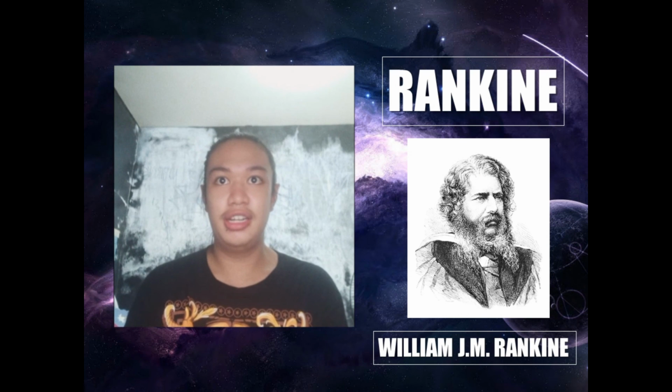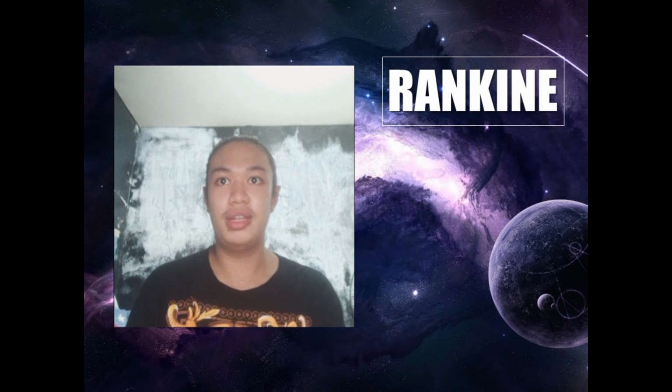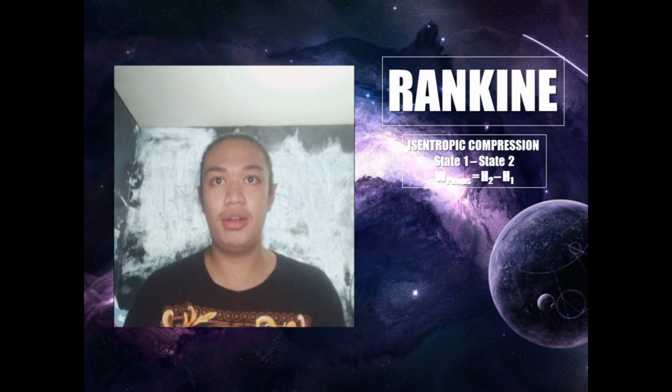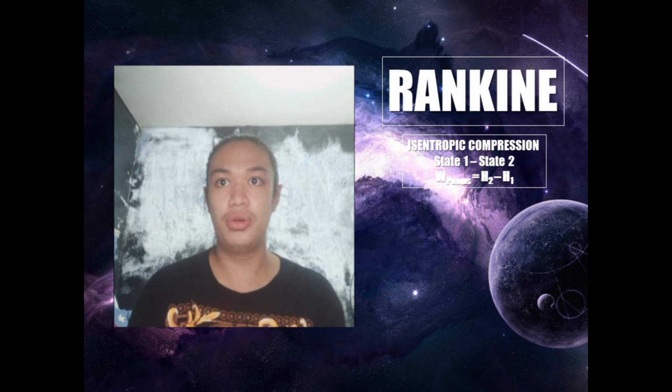A Scottish engineer, William J. M. Rankine, described and developed the cycle in 1859. This thermodynamic cycle consists of four main steps or components. Isentropic compression is the first step in Rankine. In this process, the surroundings do work on the fluid, increasing its enthalpy and compressing it. On the other hand, the entropy remains unchanged.